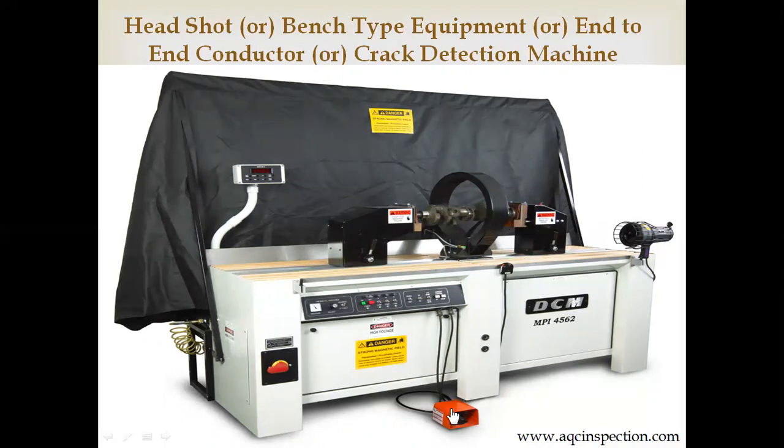There is a foot switch to apply the current. There is a black light or a UV lamp. There is a black light intensity meter. There is a digital ammeter and a darkroom setup. You can notice there is an additional setup called a rigid coil.